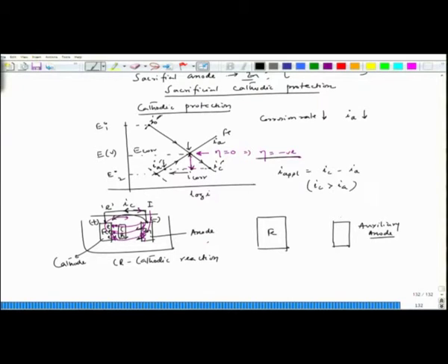Now, if I connect it to external, this is below the soil, and if I connect this end with a DC power source, this is the negative terminal, this is the positive terminal. So, electrons are going to iron and current is flowing to this auxiliary anode.